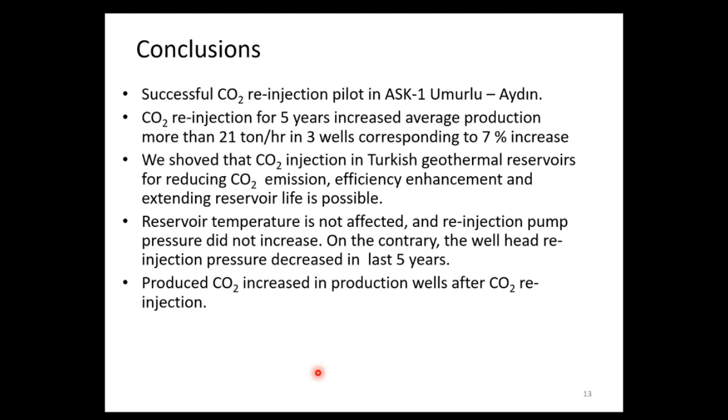It keeps continuity, not decreasing. Maybe in the first duration it looks like it's increased, but after a while it's going to stay constant, since you are not producing any carbon dioxide. Like brine, you circulate the same one. You're keeping your chemical, or let's say fluid, composition in the original state. As you know, in all geothermal systems, at the beginning it's very powerful. Step by step it comes down. You have to put in a pump or some artificial production. But if you're able to manage from the very beginning, at the level of speed your well is coming artesian, you can keep your well flowing forever with a natural flow if you're able to manage to re-inject NCG.